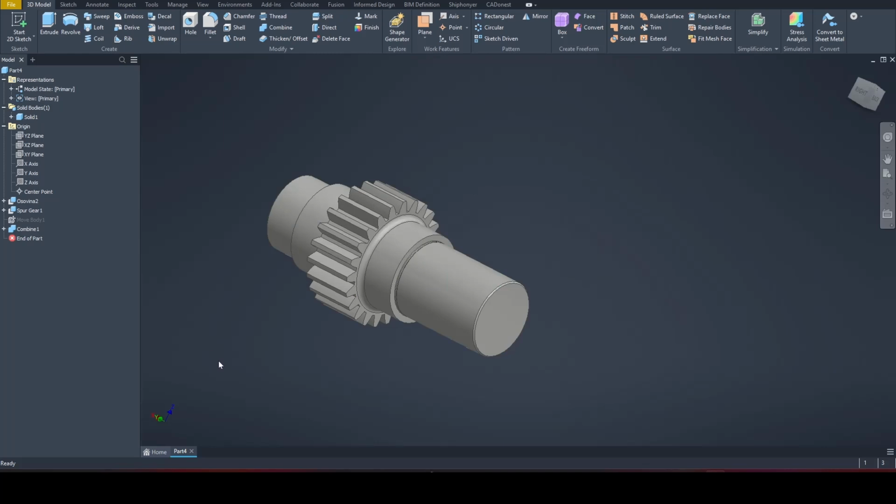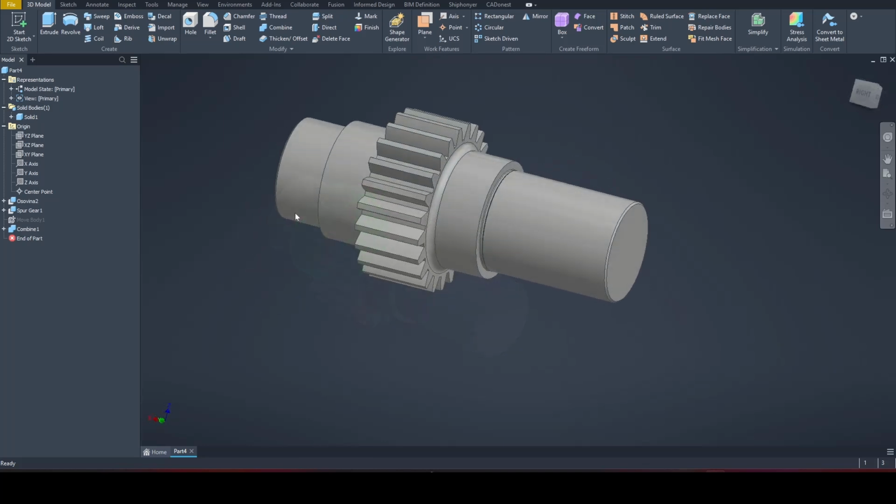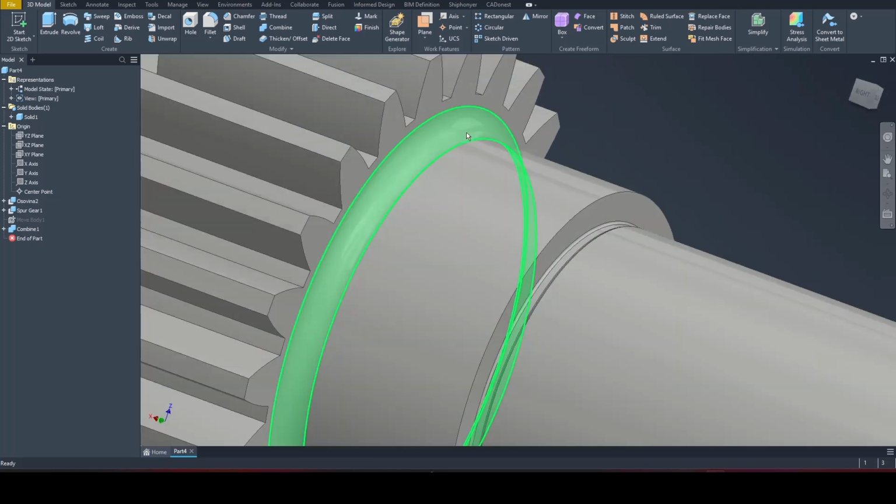First of all, you are using components that you can calculate. Inventor's calculator is very reliable. From the gear calculation, you can obtain the forces acting on the shaft. Then, you can run the calculation for the shaft and determine the forces acting on the bearings. After that, you can calculate the bearings themselves. Another advantage is how easily you can modify the geometry.